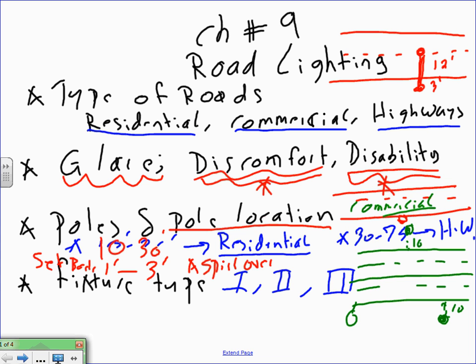In my understanding, Bloomington is really tough with that, so you have to send your calculation to them, and they call it 100% cutoff. They go there and measure the actual foot candle on the people's property, and if it exceeds certain values, they might ask you to change the type of fixture you're using.